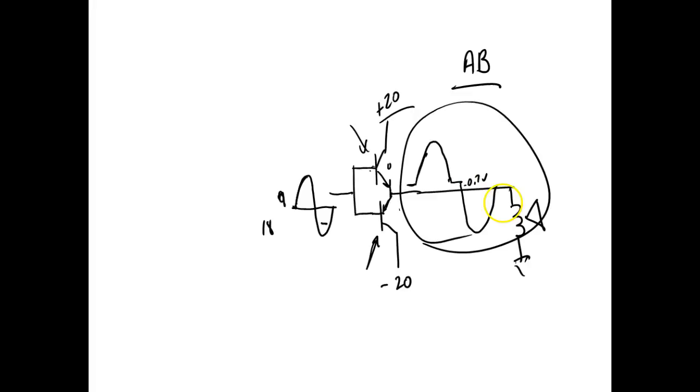So if I take two transistors and just hook them like this, we'll get that crossover distortion. I'll hook this up just the way it is now, and then later on we'll look at how to get rid of the crossover distortion, and then we'll look at some actual power amp outputs, and you'll see the same circuit. It's not that hard. Just use a few diodes.